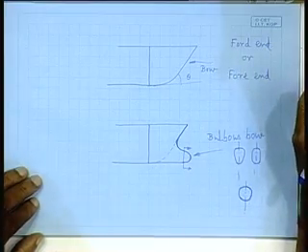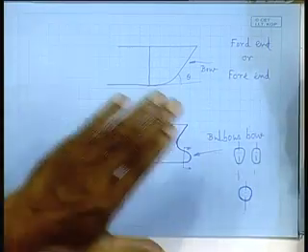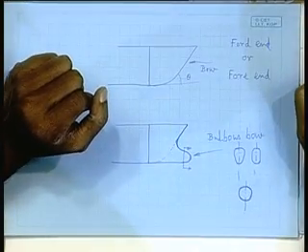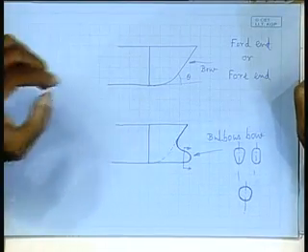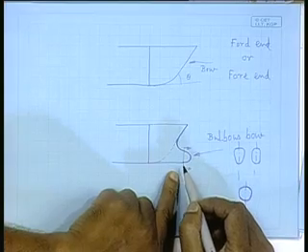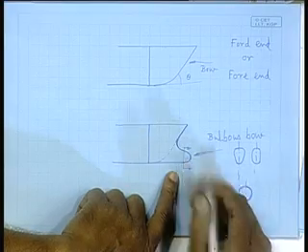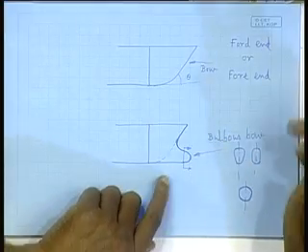In one sentence, it can be said that providing a bulbous bow reduces the resistance of the vessel. Resistance means resistance of motion. When the vessel is plying through water, the water medium offers resistance to its movement. So our objective is always to reduce that resistance to a minimum, because then I can have a very efficient propulsion and our fuel consumption will be less. So this is one of the ways of reducing that resistance, by providing a bulbous bow. How that happens, we will learn later.